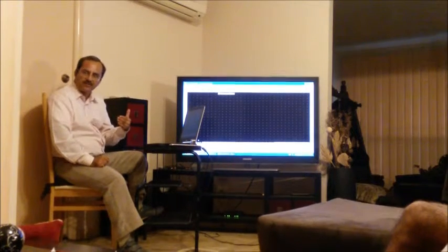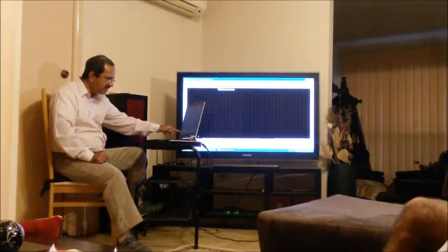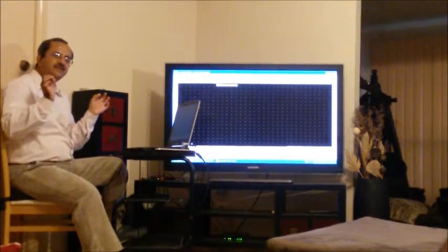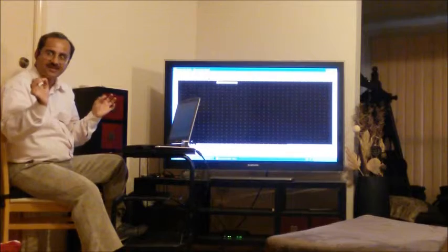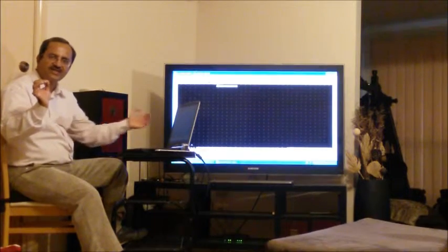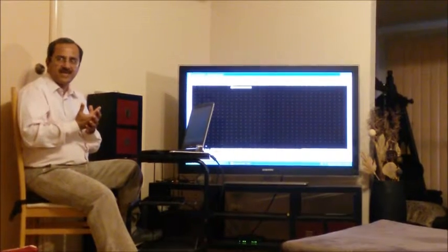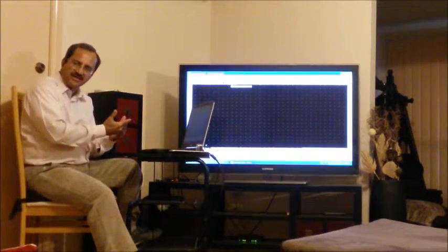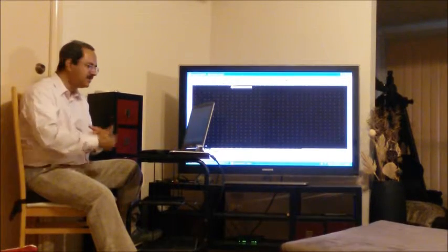That means AutoCAD knows that you selected line, you want to draw a line, and then it says specify first point. And we know that if we want to draw the line, we have to give 2 points. So it is asking me the first point. This is how AutoCAD is asking questions from us, and we have to give the answer accordingly. We are getting a hint of what the software expects from us.